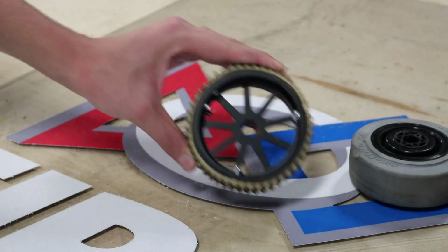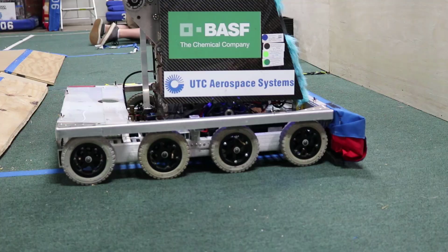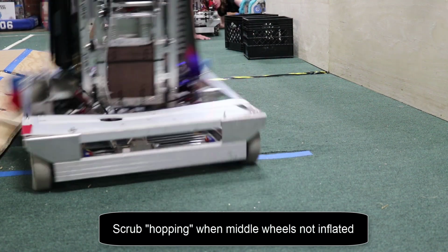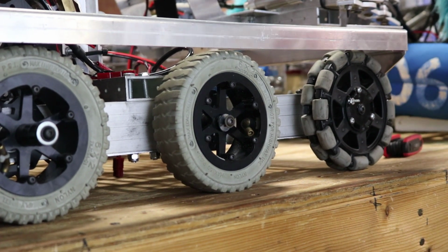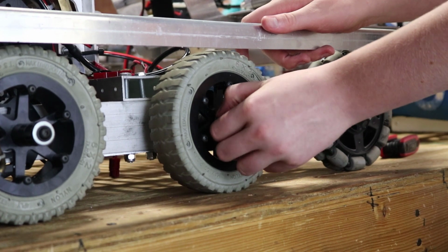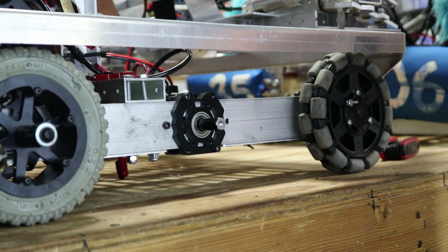For 2018, we actually tried 1/8 of an inch on our 8-wheel drive 6-inch pneumatic wheels, and we scrubbed a fair amount. So we inflated the tires in the center more and deflated the outer tires a bit, and this small difference made an important impact on our turning performance. This was not as noticeable for us once we made this change, but in hindsight, a larger drop of 3/16 or 1/4 of an inch would have been better for our small pneumatic wheels. Once you go up to the 8-inch pneumatic wheels, the drop is probably going to need to be adjusted.